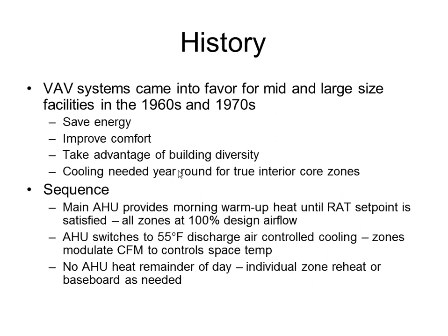Again, it does not go back into heating mode other than the morning warm-up time, because a VAV application requires cooling all year round. So your air handler discharges, say, 55-degree air for the rest of the time, and each of the zones will modulate their damper based on that 55-degree air coming in. And again, no heat the remainder of the day.